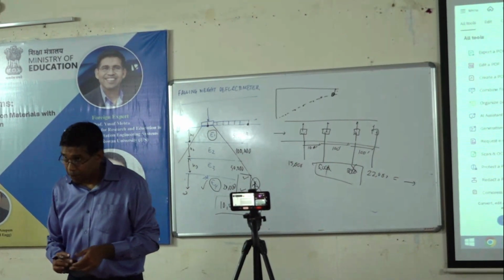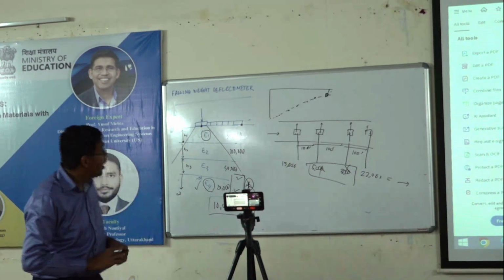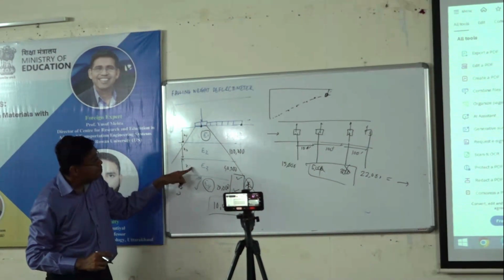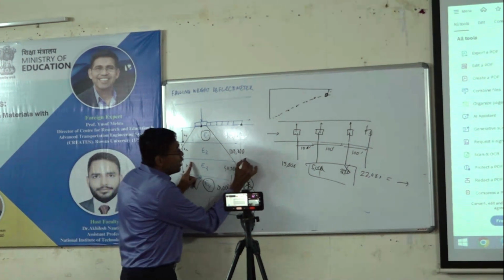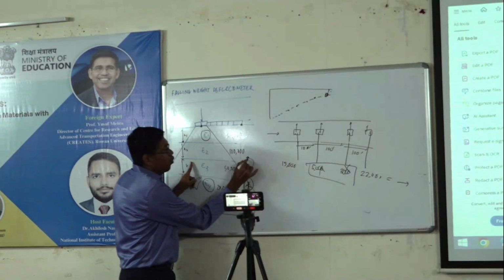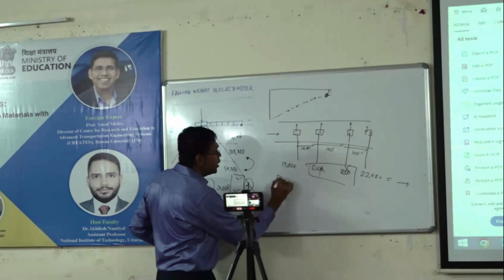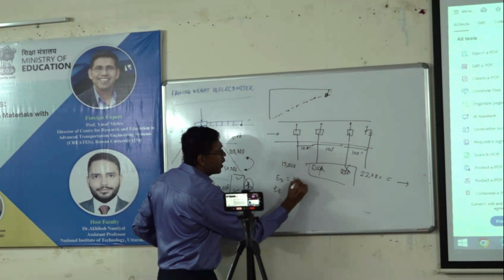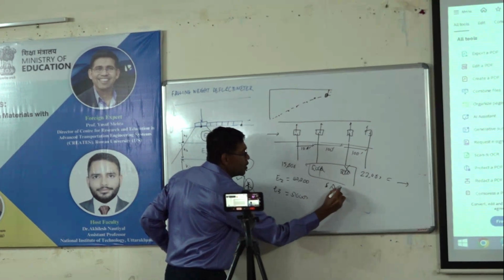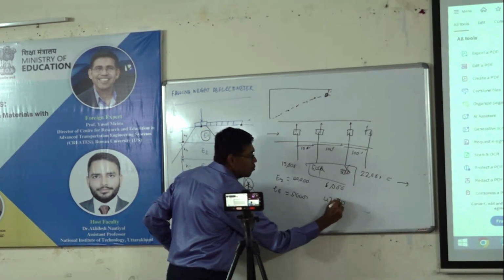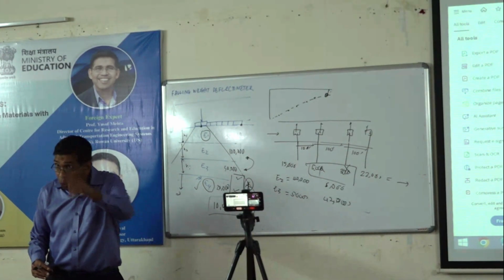Pretty big news so far. Couple of things that will happen, very common. If these thicknesses are very small, one of them are very small, they will tend to swap. I'll explain what this means. That means in one of the sections, mathematically, E2 and E3, one will show 40,000, one will show 5,000. Next section, this will show 6,000, this will show 42,000. So on and so forth. So mathematically, it is not able to lock in, it is just swapping the numbers.